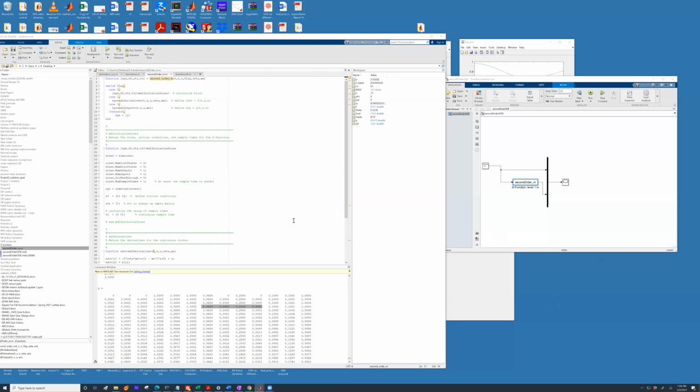Okay, now I want you to listen to this discussion very, very carefully. Simulink has the capability of taking an M function and converting it into something called an S function, where S stands for Simulink function. It could be a level 1 function or a level 2 function. The purpose of the S function is like a wrapper.